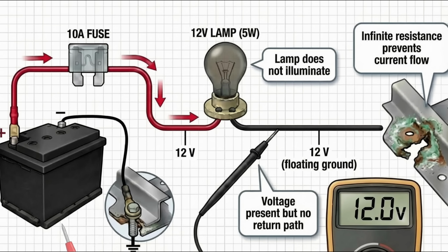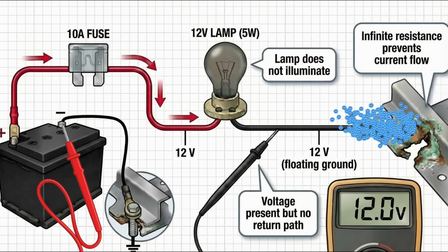And here's a final diagram for you. There's our positive probe. We're doing a voltage drop test from negative to negative. And essentially we've got our 12 volt there, essentially, instead of 0. And the reason we've got that is because we've no ground return path. And there's our lovely electrons, negatively charged, sat there. They can't go anywhere. They're basically just electrical pressure, there's voltage, and they're going to sit there because they have no return path.